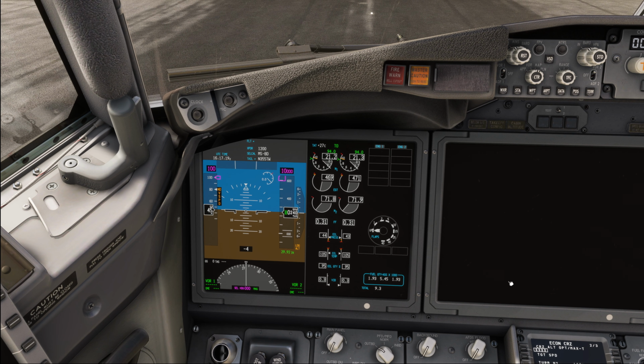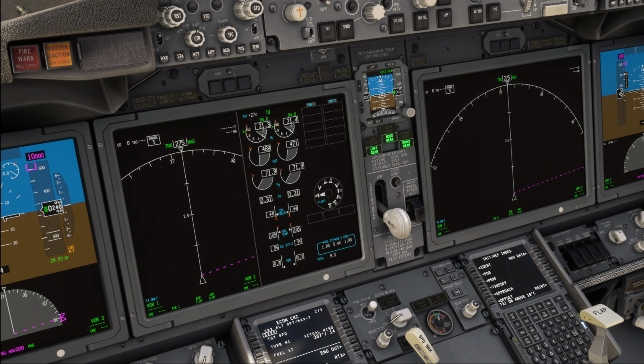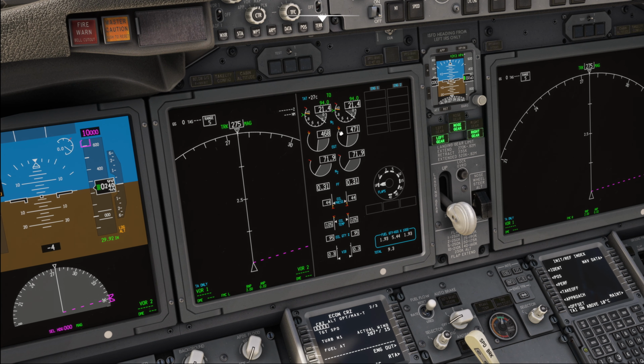Alright, moving on to our inboard display unit then. Let's go back to the normal display indication over here. You have already seen that we can switch the ICAS around. So we can have the ICAS either on the left side or on the right side, but not on both sides at the same time. It's either one or the other. In my former airline, it was SOP that the pilot flying would have the ICAS on his side so that he could handle the thrust with a quick glance.